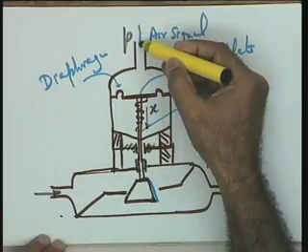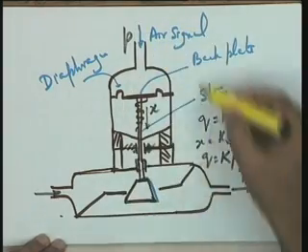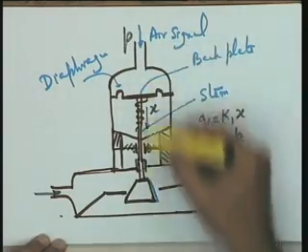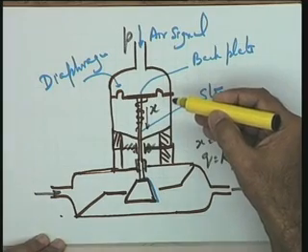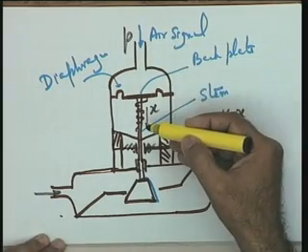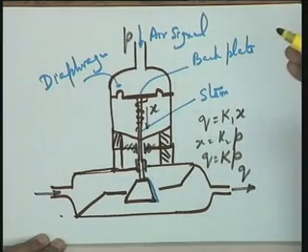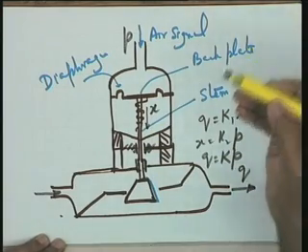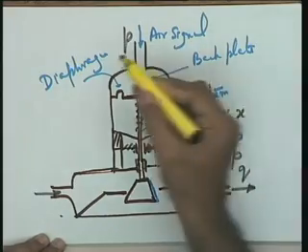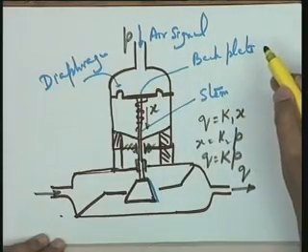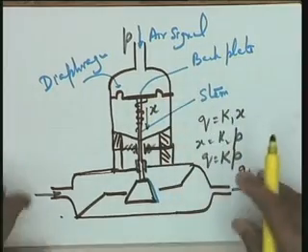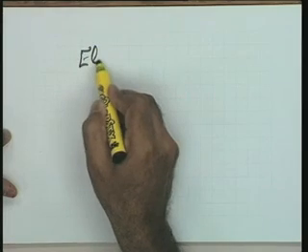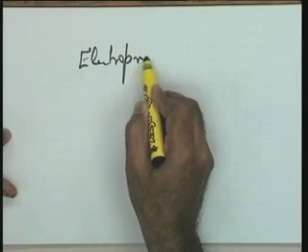You require a pneumatic signal, an air signal, because you want to use this pneumatic device for controlling the stem position. You do not want to use a solenoid. You want to use this particular device, while your controller is going to be a digital computer or an electronic device. So in this case also you require a suitable interface between this device and the electronic controller, and acting on similar lines is an electro-pneumatic transducer.